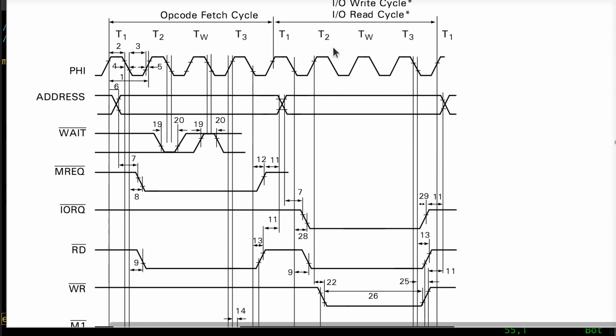So what we want to do in the reading case is make sure that we, as a peripheral, are submitting a stable signal starting on the falling edge of T2 and hold it as long as these guys are on there, okay? So what I need to do is the same thing, but I want to see it around T2 instead of TW. Now, in the simplest case, you might just say, well, just go true during state 0. Because during write, we went to state 1, which is this, and logically that must be state 0. Well, yeah, except for one thing. State 0 is over here too.